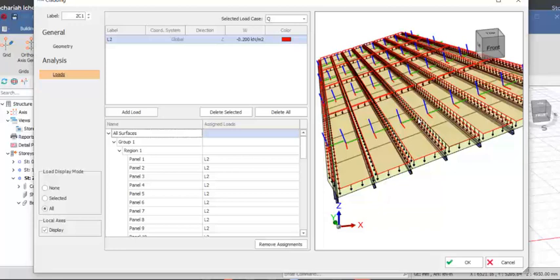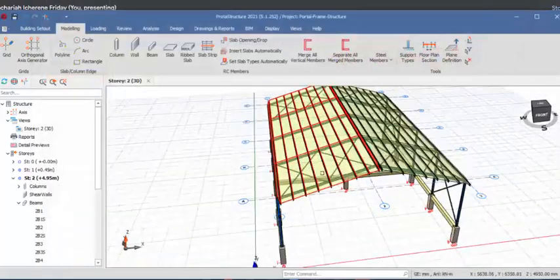Having done all of this successfully, just as I said earlier, if you want to apply the wind load, you can always use this WX and WY manually, just the way we applied the Q load and the G load. Click on the OK option. So we have successfully loaded this face of the roof.